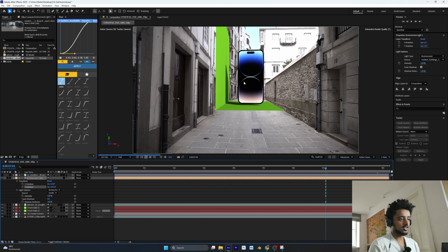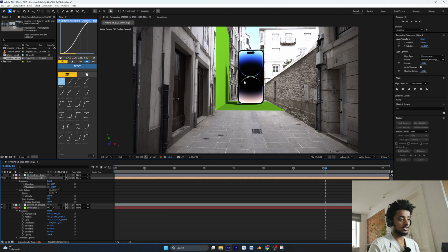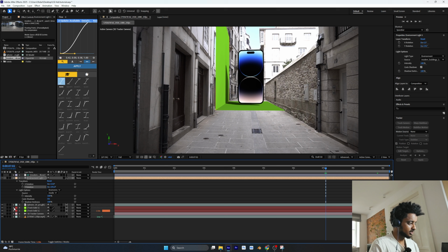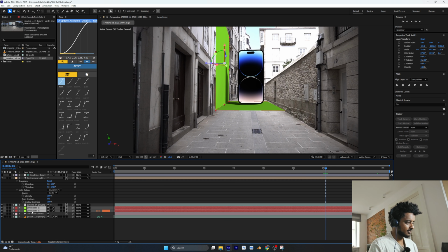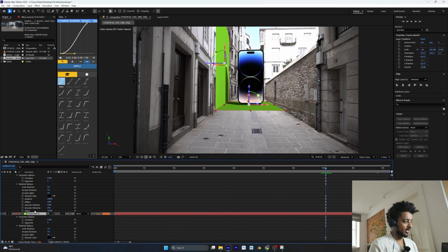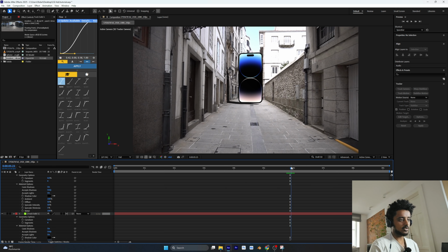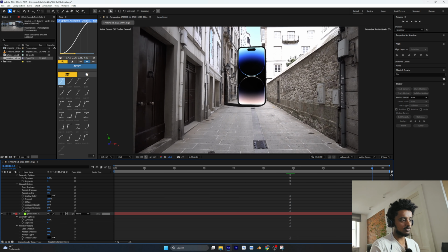Now, as you can see, it's floating here and we get the shadows, but we want to remove these solid objects. So the way we're going to do it is, let's go to our solids here. I will select both of them by control clicking, and if you press AA, you can actually go to cast shadows and accept shadows. In the accept shadows, if you press Only, then it's going to remove the solid colors and preserve only the shadows. And now we can try to play around with the shadow here.